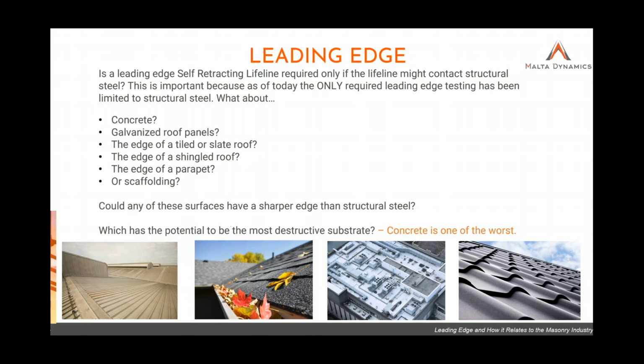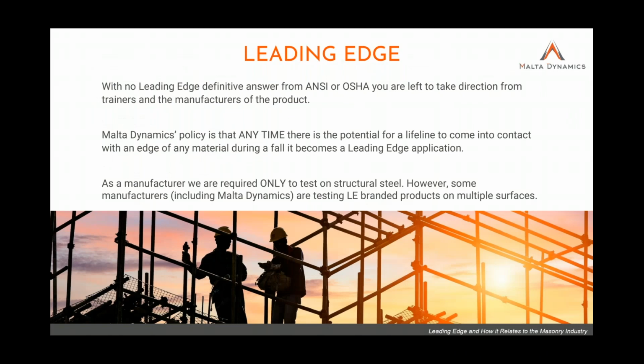With no leading edge definitive answer from ANSI or OSHA, and this has been going on for a long time now, you are left to take direction from trainers and the manufacturers of the product. Malta Dynamics policy is this: anytime you have the potential for a lifeline to come into contact with an edge of any kind of material during a fall, it becomes a leading edge application. As a manufacturer, we're only required to test on structural steel. However, some manufacturers, including us, are testing our leading edge branded products on multiple surfaces. And again, I'll reiterate, our engineers are finding concrete is the most destructive.